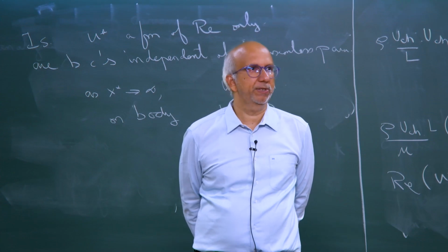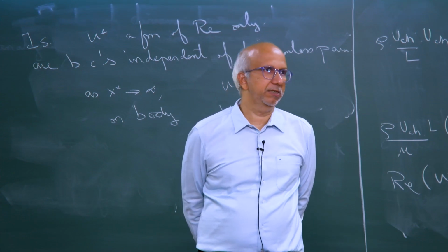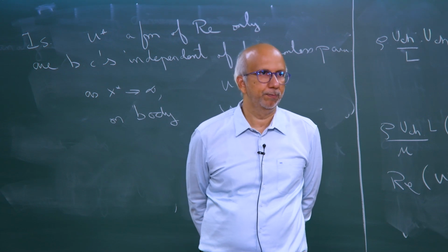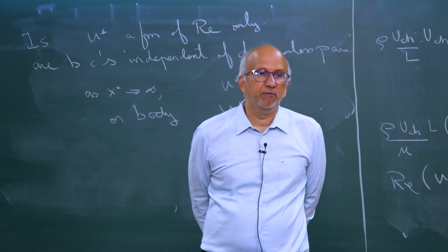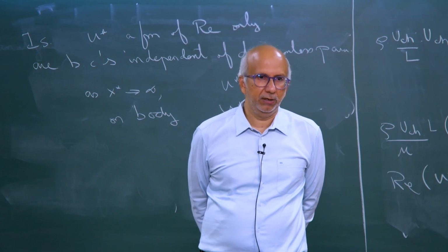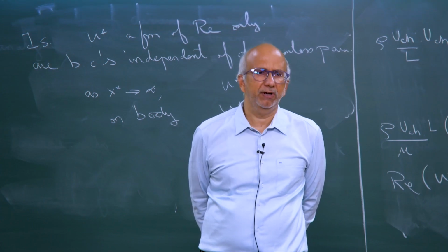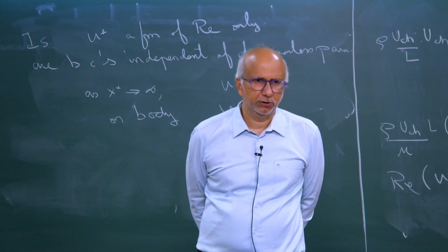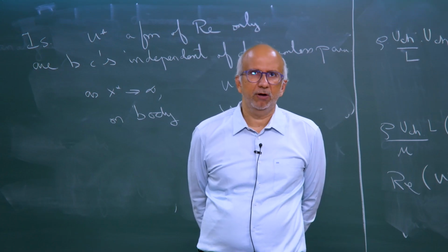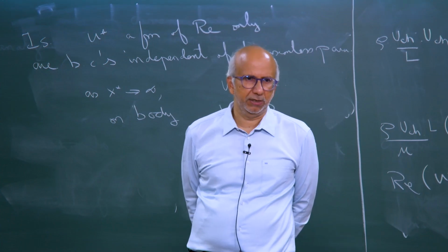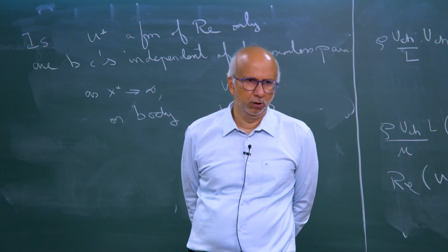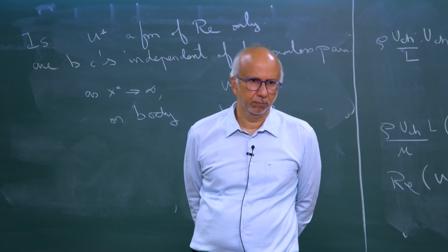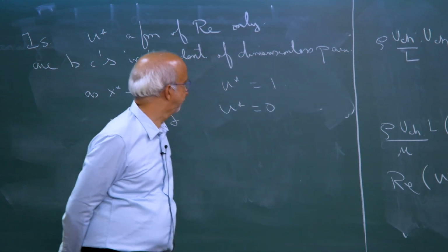So you will convert this to equations which have only the velocity field, and then you can solve like we did before. You can eliminate the pressure if it is a 2-dimensional flow, and then you can solve. So what I am doing is specifying the velocity, and that is enough for me to solve the problem.